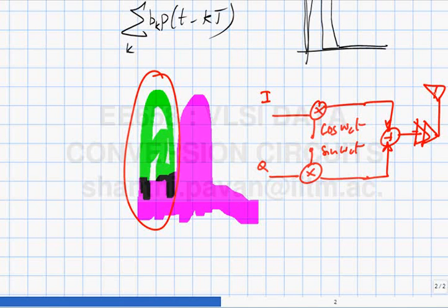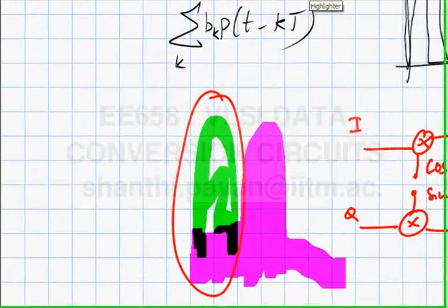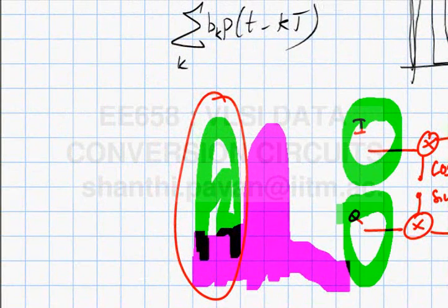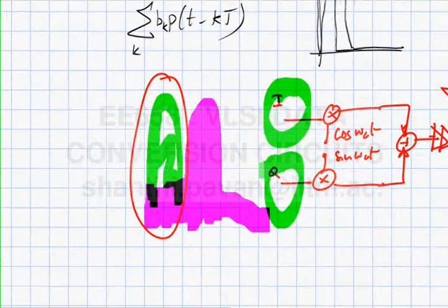So what you do is you want to make sure that these waveforms have sufficiently smoothly controlled slopes so that you manage the spectral width properly. That's all this BPSK, QPSK, all this other stuff with the raised cosine pulse shape is doing. What they're all doing is managing the spectral shape.